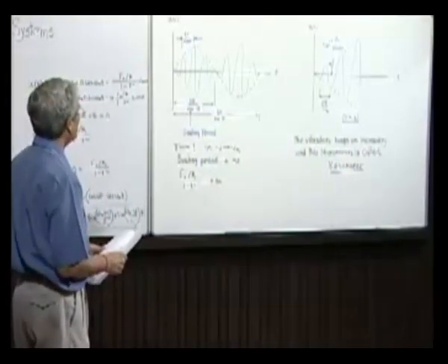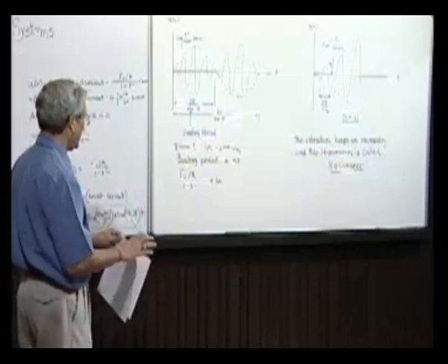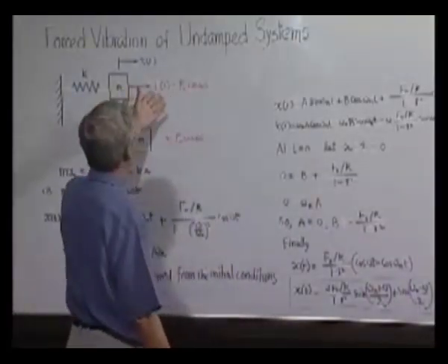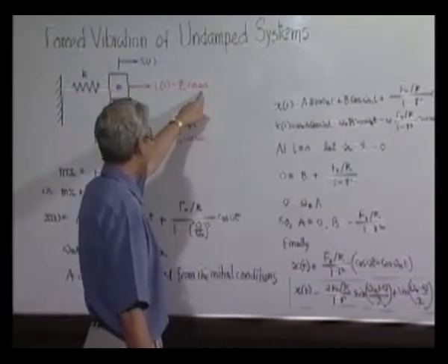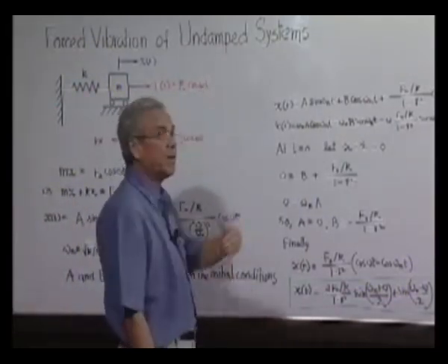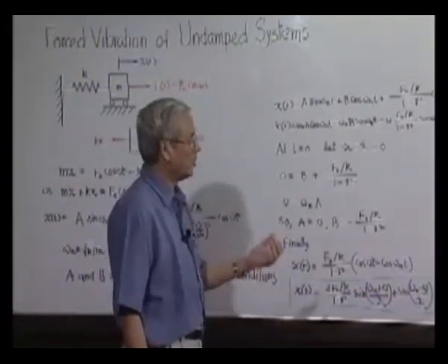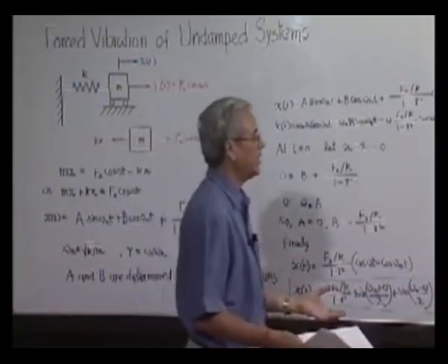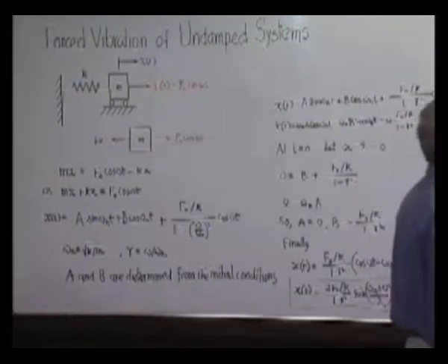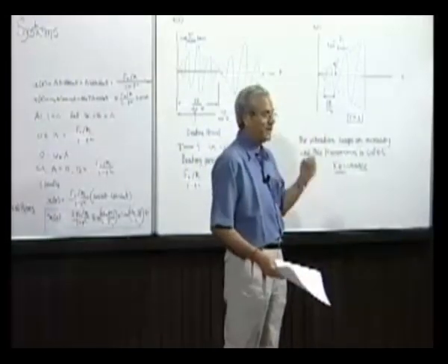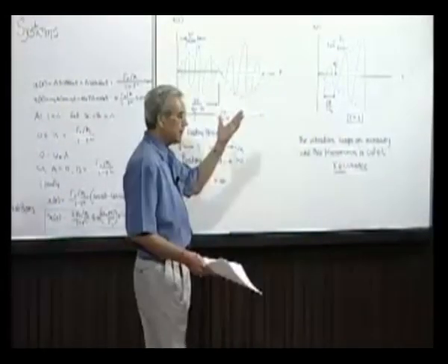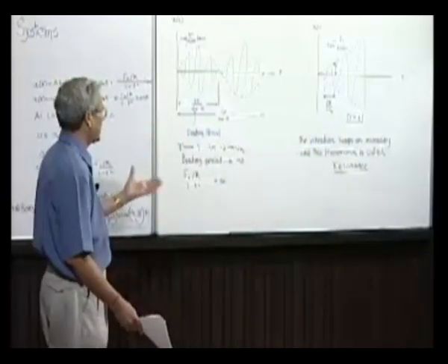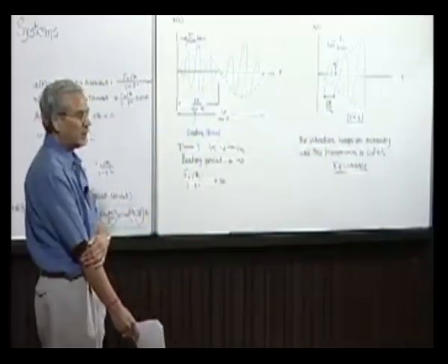That is why we should remember our earlier caution: when a forcing function is acting, we should be careful that the forcing frequency never goes anywhere near the natural frequency of the system. That is why when something is being designed, its natural frequency should be estimated, and it should be ensured that the system is never subjected to a forcing function or excitation where there is a chance of resonance.